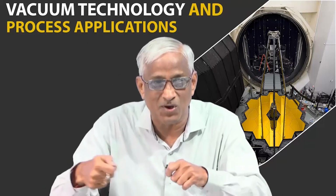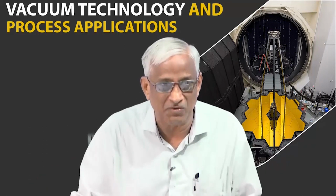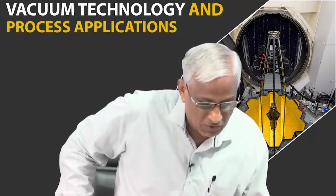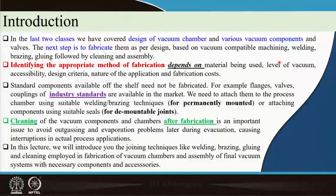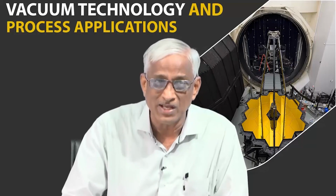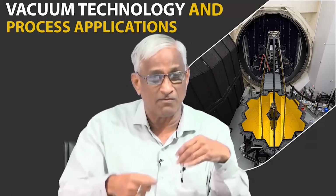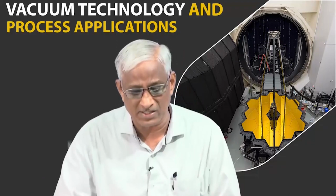Welding is not just the small TIG welding that we see in the day-to-day world for our household welding, etc. That is what you have to see. And cleaning is not just some cleaning with soap water or water. It has to be done with deionized water, then purging with high pressure pure gas, then ultrasonic cleaning. All these things have to be done to remove dust and water or various other contaminants.